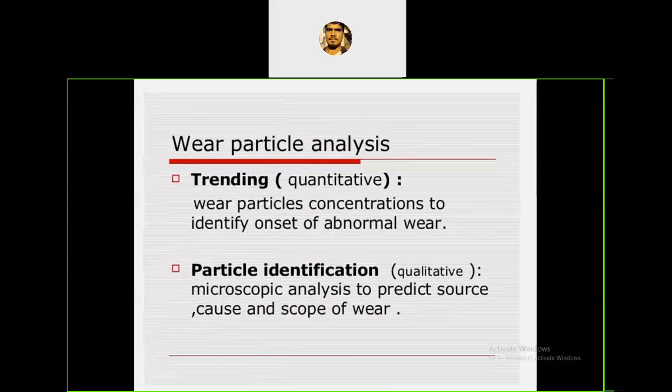Okay. So the wear particle analysis. If you go with a particle analysis, there are two types. One is a trending type, which is quantitative wear: the wear particle concentration to identify the onset of abnormal wear.